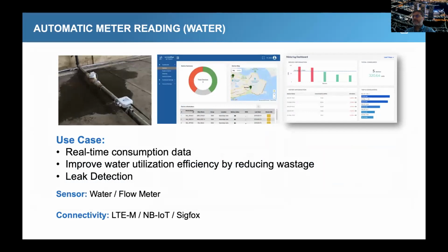And they had issues around leakages, abnormal consumption, reporting to the regulator on their consumption, and everything was done manually. And they had meters already. So what they did was they connected the meters to our device, as I mentioned previously, using a bunch of wires. So it gives a pulse signal. And every 4 hours, we measure how much is the total water consumption, transmit it to our cloud, and do the further analysis depending on the business use case, right?